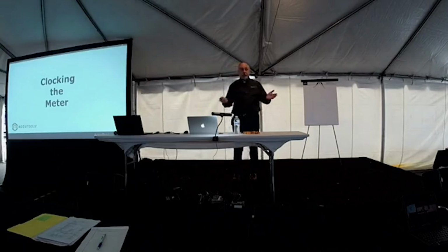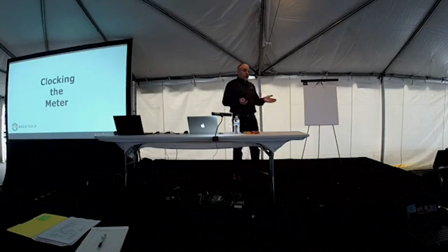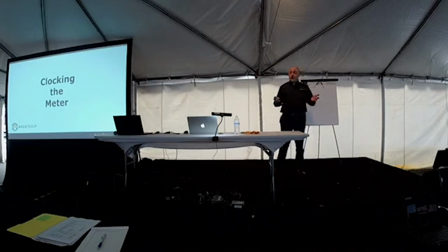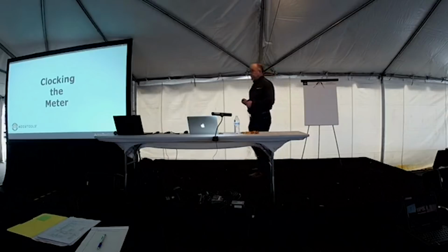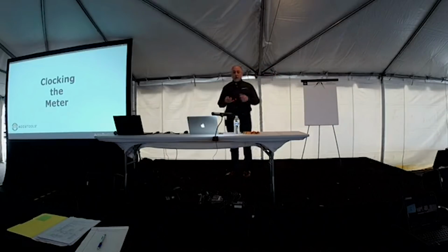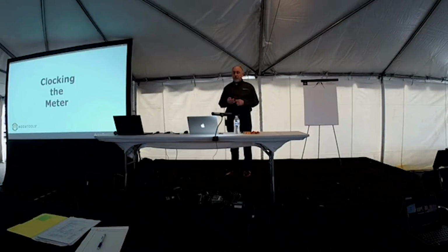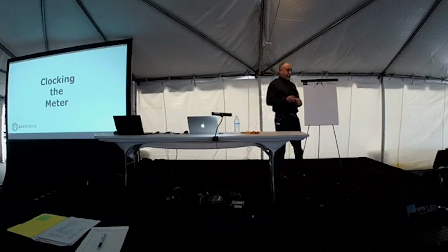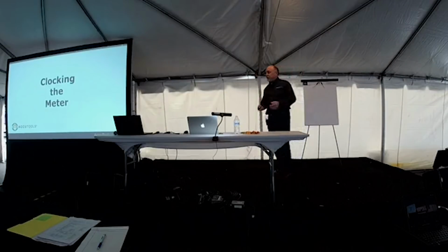If you think about it, there's not too much we can adjust on a natural gas appliance. In fact, there's only two things. What are the two things we can adjust on a natural gas appliance? Input, gas pressure is one, and what's the other one? Airflow. Blower speed. That's it, right? Guess which two things don't get set correctly in most appliances? Gas pressure and airflow, right? That's the stuff everybody forgets about.